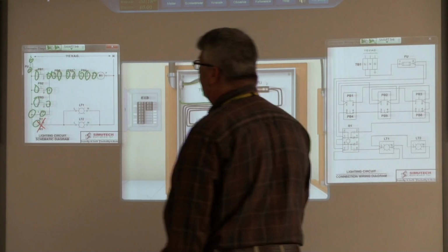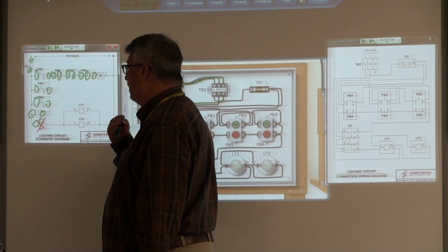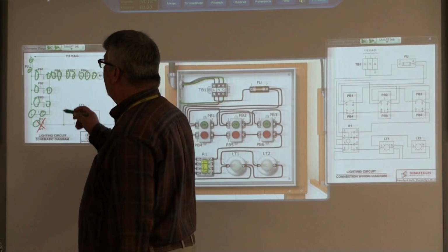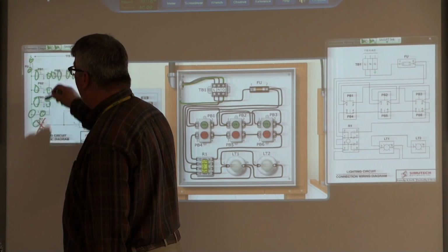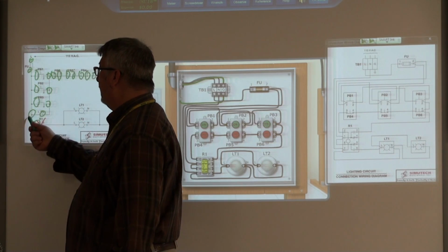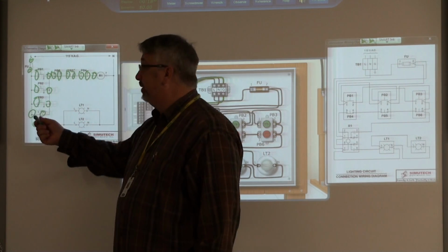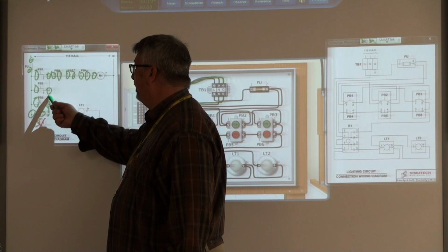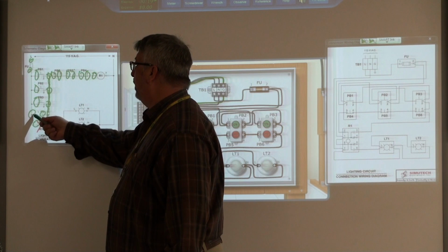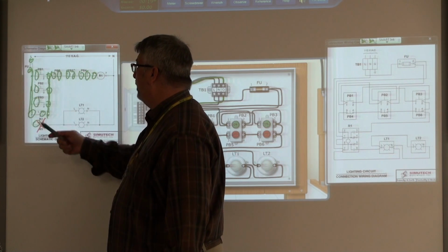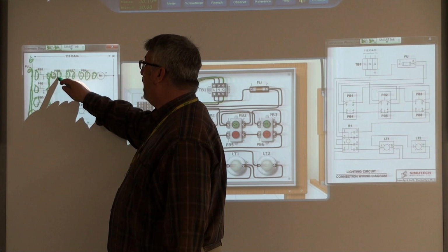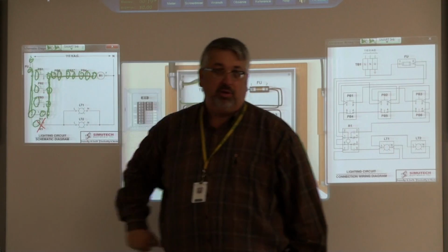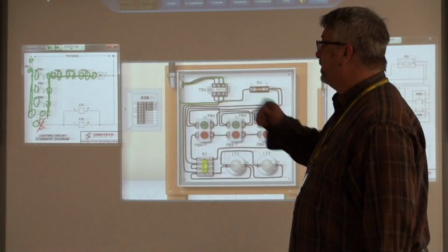Because what's happened is, the only thing that changed state is that relay contact, which it should have. So when we press PB1, PB2, PB3, and if 1 and 3 close, then this 115 that's here is at the same potential here. So that puts 115 volts in this entire line. We've already got 115 volts up that entire line. None of the off switches are pressed. So we've got 115 volts all the way to pin 2. We've just got a relay.